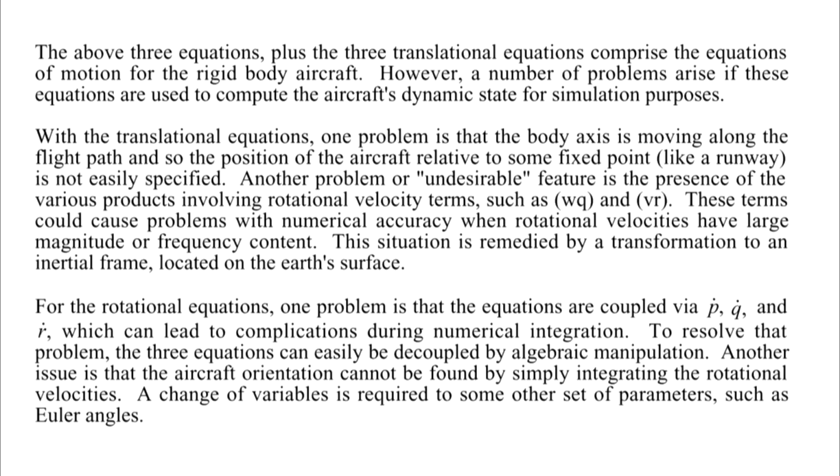Another problem, or undesirable feature, is the presence of various products involving rotational velocity terms. These terms could cause problems with numerical accuracy when rotational velocities have large magnitude or frequency content. This situation is remedied by transforming to an inertial frame located on the Earth's surface.